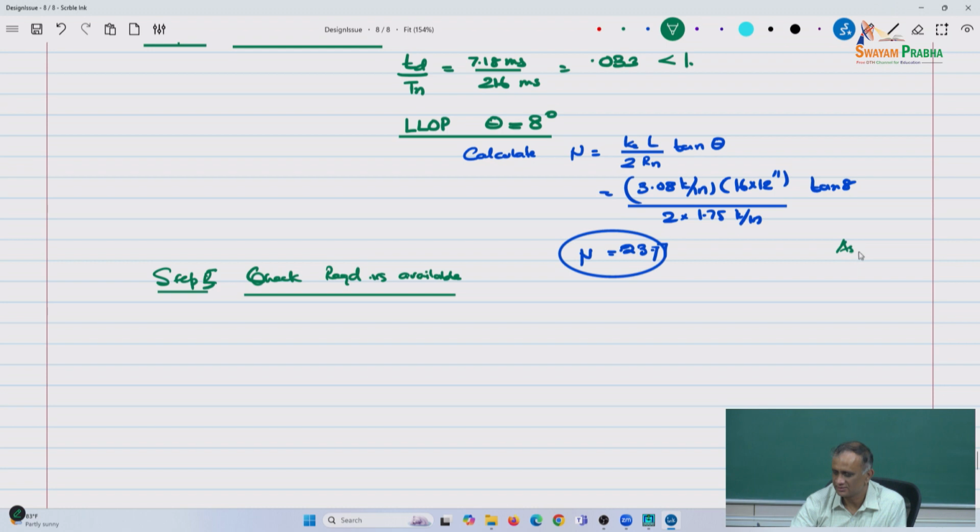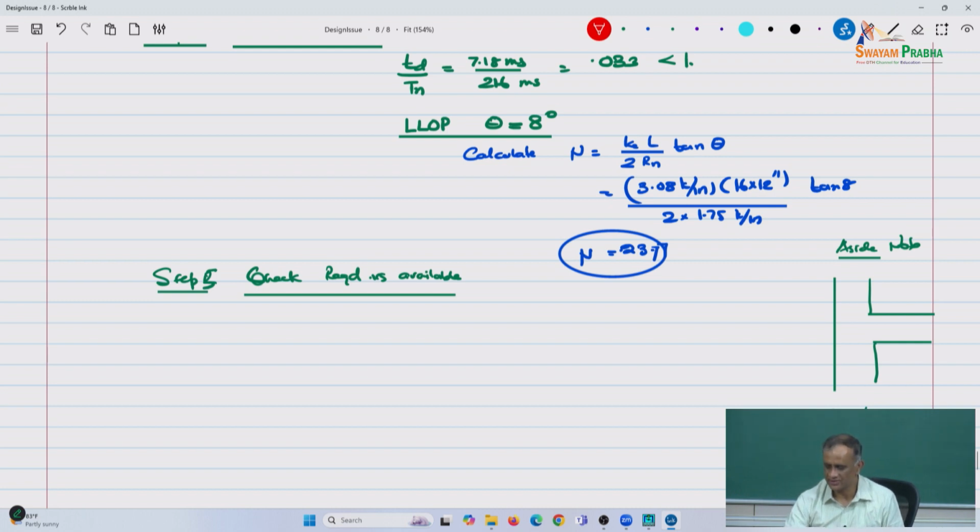For example, you might reinforce a column. So this is a side note. For instance, if this is your regular loading like this, and suppose you have a reverse loading. Now what is it going to do? It's going to open it up. So you might change it to something like this instead, right? So when it is going up, this will come into play. When it's coming down, it would close in rather than open up.